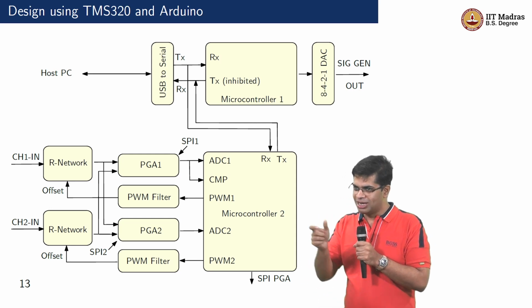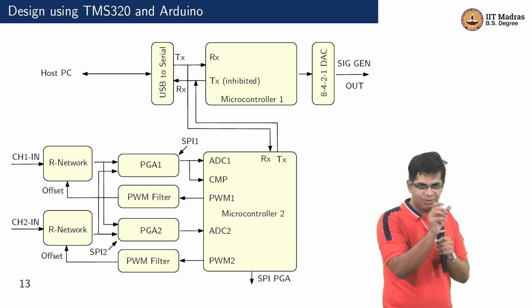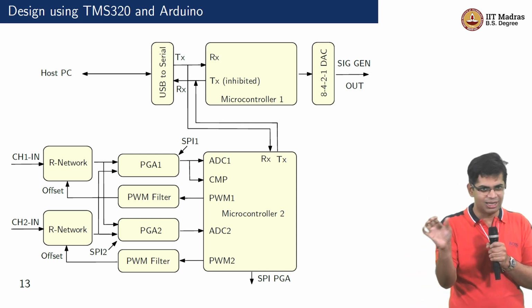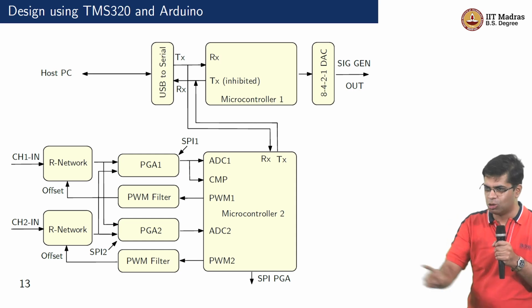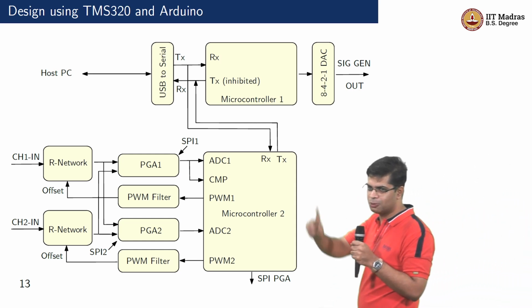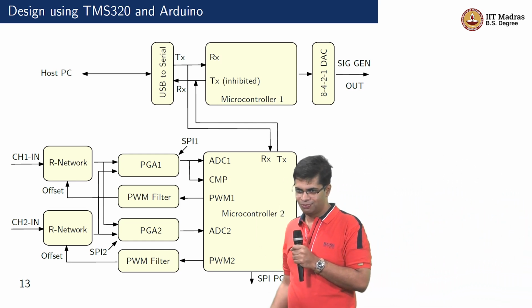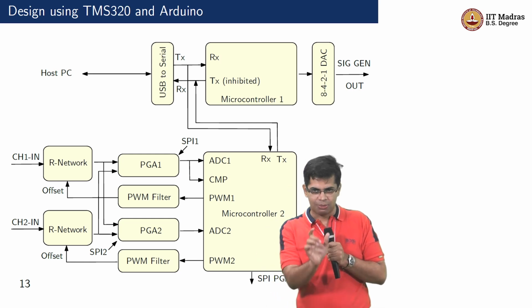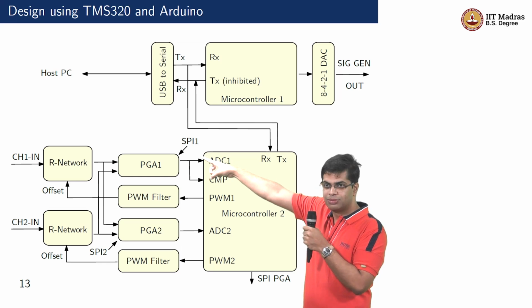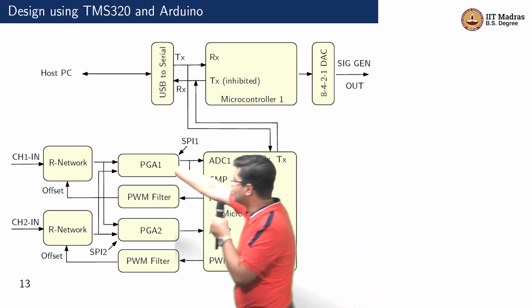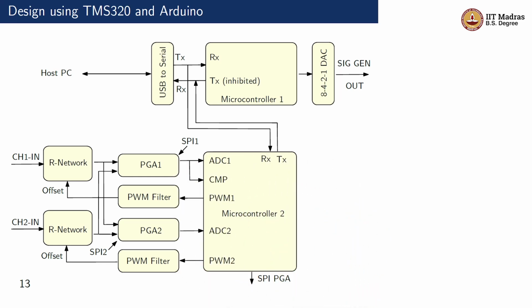Okay. But the data I send is tagged, because every serial stream, I can put whatever I want, right? So I say this particular command goes to the Arduino. This particular command is supposed to be for my TI chip. That way I tag the commands. The commands come to both. Both of them receive. This fellow is receiving, and this guy is also receiving here.